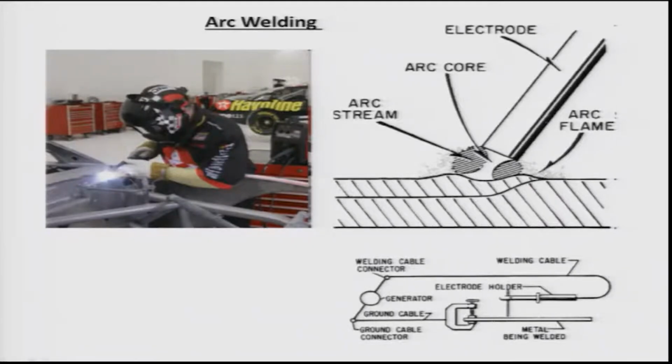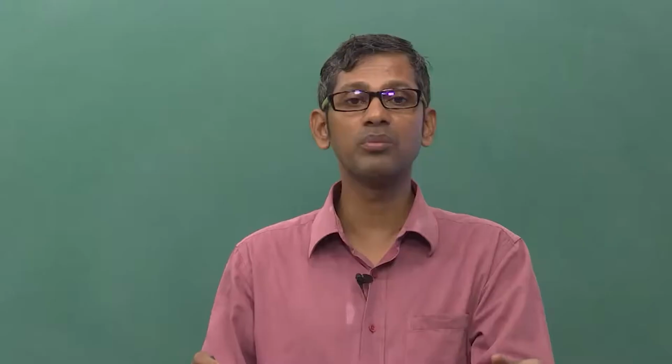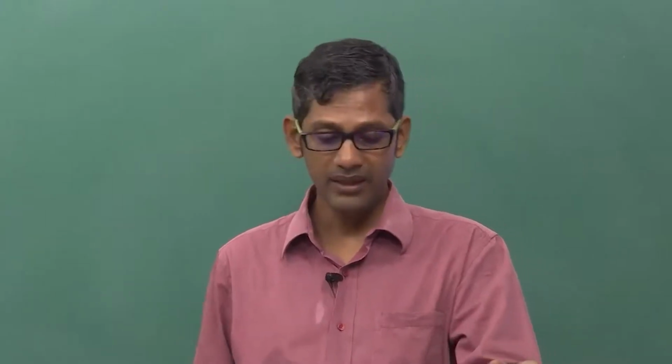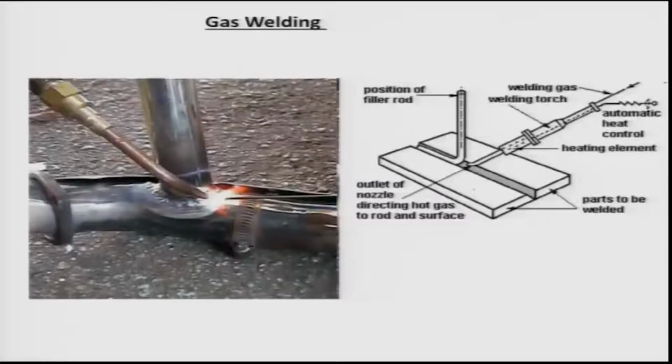The important aspect is how the grains then grow, because this welding torch moves at a certain velocity during the welding process, as you have probably seen welders do when welding pipes or other objects in different places. So the more important aspect is how the growth of the solid happens in the liquid.